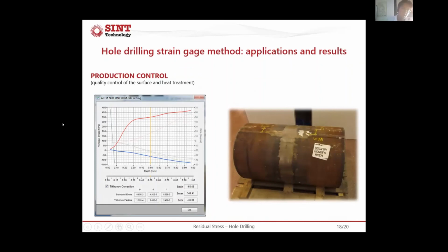of megapascal. That is a very crucial and big value, also because it is tensile stress. This is typical trend of the residual stress in a welding area. We can have tensile stress in particular in one special direction, depending on the welding technique. And the residual stresses can be very dangerous and very high here, because of course, as we said at the beginning, if we consider the contribution also of the external load plus the residual stresses, this is a value that can be very dangerous for the customer.